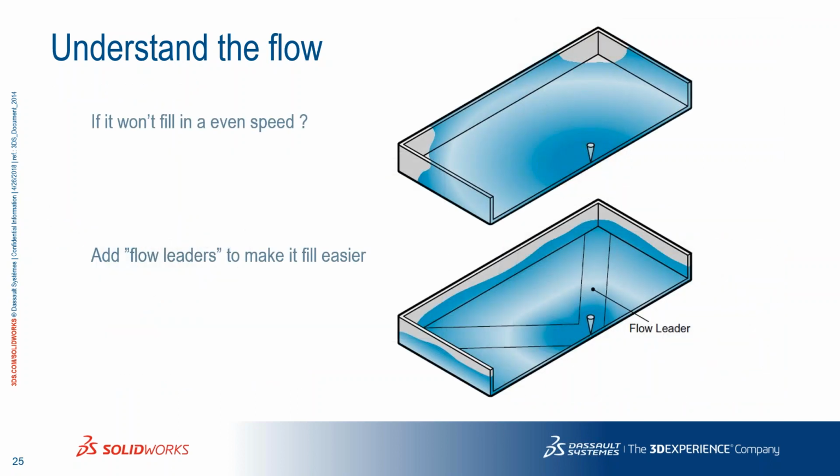Just to finalize here, if you're opening up some plastic parts and you look inside, and maybe you can see some ribs, you might think that, yeah, that's for reinforcement of the part. It will be stronger. Yes, it will. But maybe the ribs are only there for manufacturing purposes. So if you have a gate here in this center, the end will fill up slower. And as I said, we want to have a uniform flow front. So there's a trick to add a little rib, a little more geometry here, to make it a little easier to flow. So we will end up with a flow front that is uniform also in the edges there. Just a little tips and tricks on how we can make things better for the injection molding process.